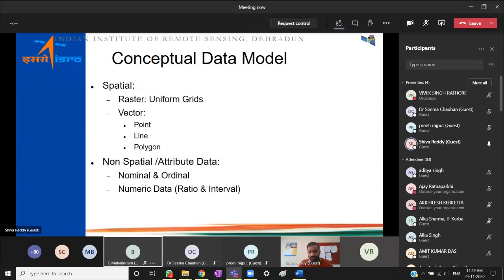So in GIS, your data can be modeled as either a point, a line or a polygon, as vector data. In the sense, if you want to store, say, the location of restaurants in your city, you can make a restaurants vector file with the type as point. Within that file you will store all the points which represent the location of the restaurants, and corresponding to each restaurant you can represent any attribute data.